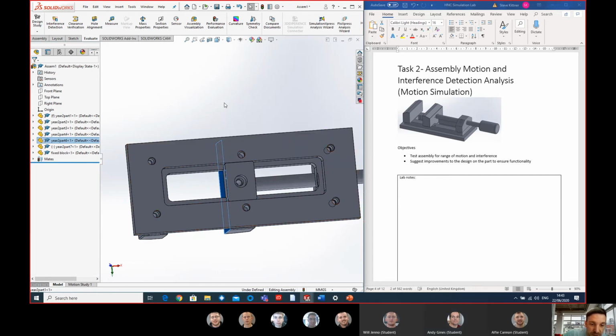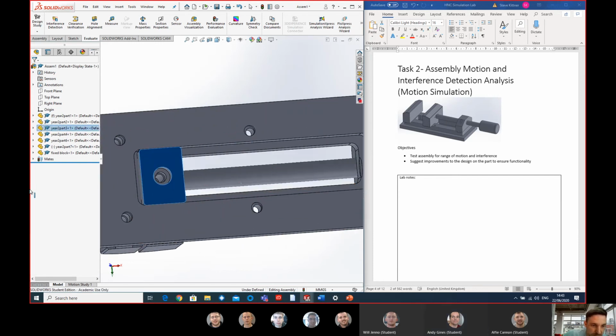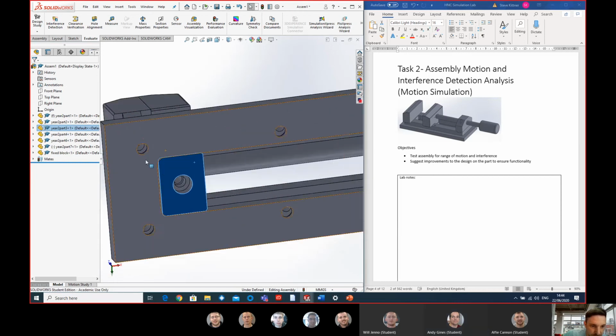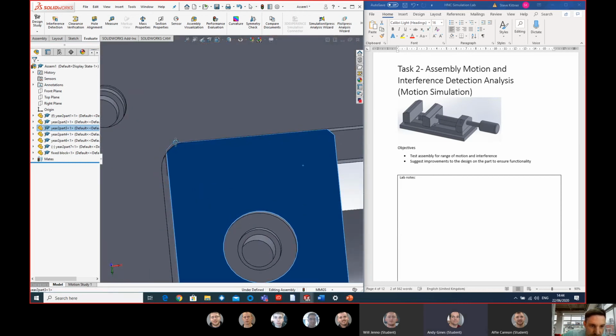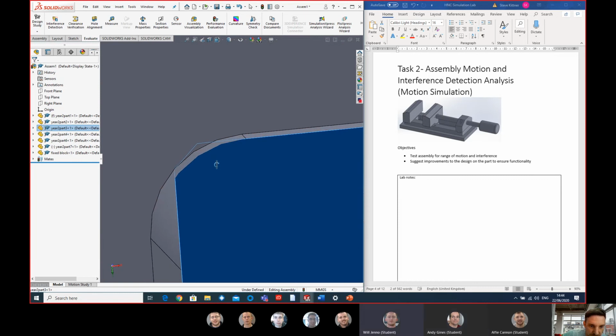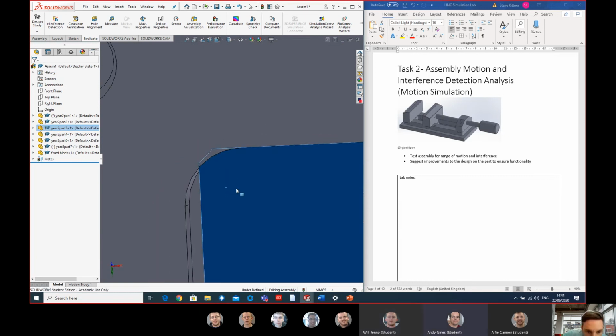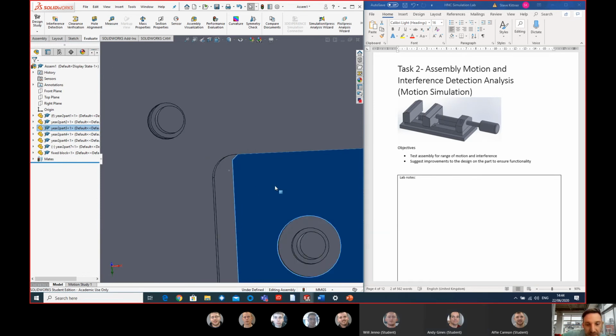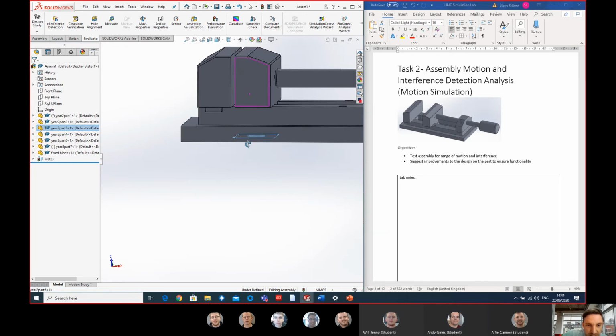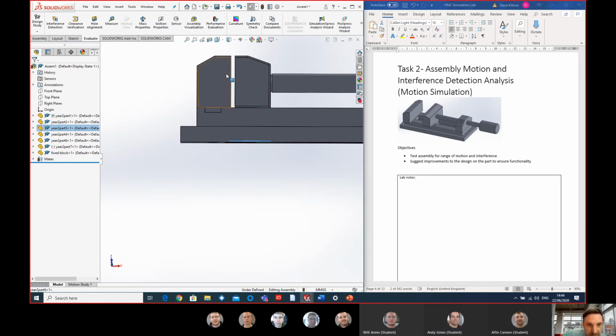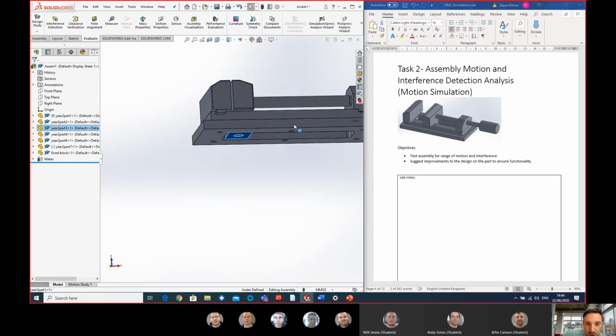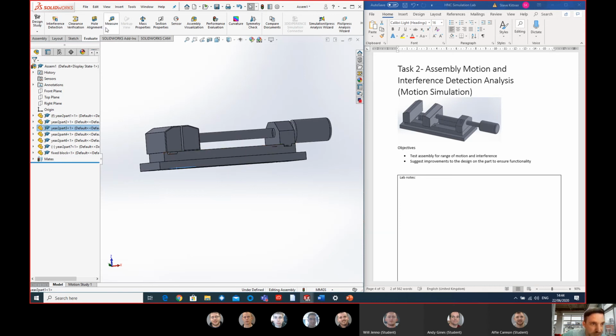What about if we, let's pull this right the way up here. So this little bottom plate. Can you see that bottom plate there interferes with that radius corner? Yeah. So some clearance. Yeah, so this would only go up to about here if we actually made this to those sizes, and you can see there's a gap now in the side of here. So one of the first things we can do when we've got a model together is do interference detection.